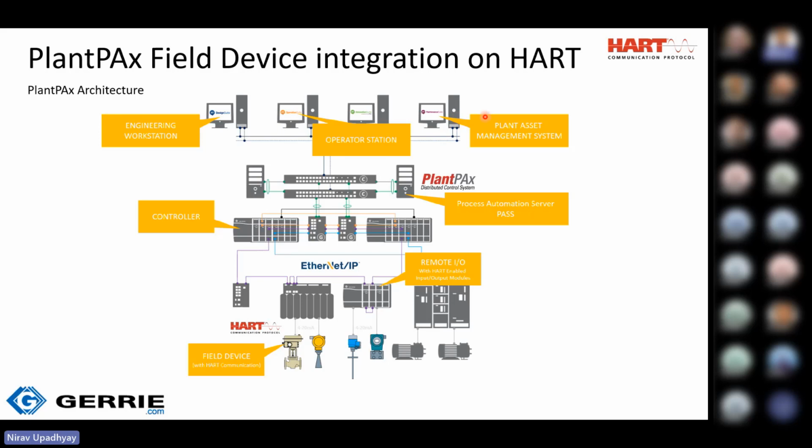So you can connect any of the options as an application server. We have clients: thick clients for OWS and EWS, the operator workstation and engineering workstation, or thin clients for remote desktop server, and thin manager options can be available. So this is a typical architecture where you can connect the HART-enabled devices to the cards, and you can control the HART-enabled devices and the system.